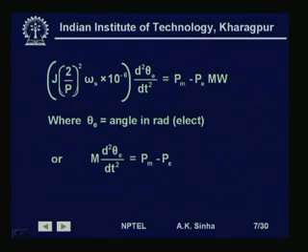This relationship is that the electrical quantities are equal to P by 2 times the mechanical quantities, in terms of speed or in terms of angle. So, we have omega sm, which we want to write as omega s. omega sm will be equal to 2 by P into omega s, because omega s is equal to P by 2 omega sm. So, we get 2 by P here.